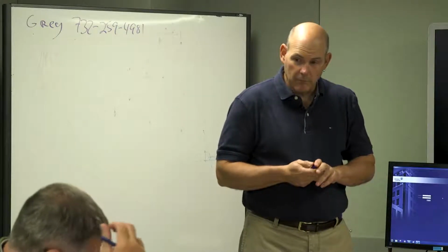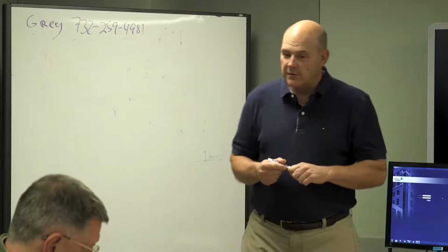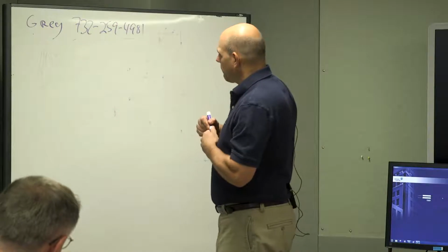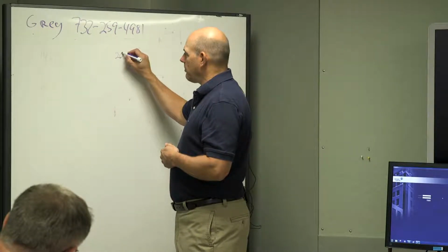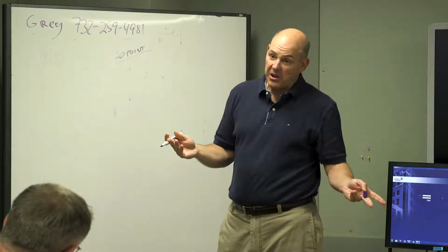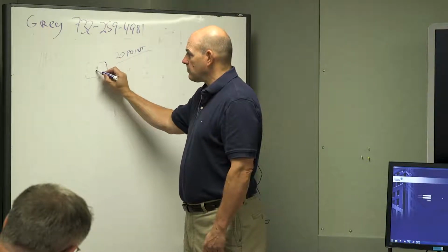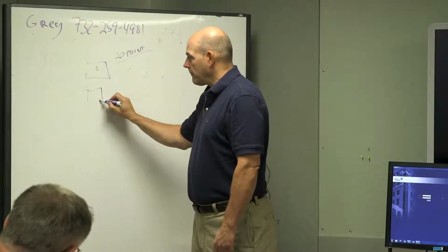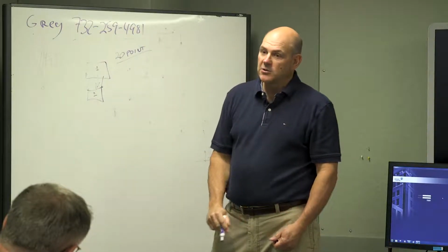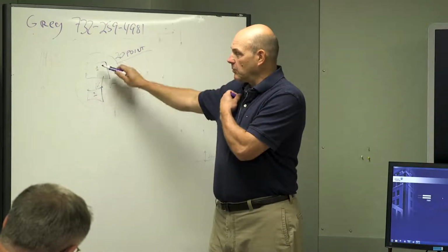For example, this is the IOM, just to make it more understandable. I'm trying to think of a good example. All right, if we have a controller that can only handle 20 points, I'm using that as a fictitious number, but we need 30. We can take this main controller here and call it address 1, and we can take an IOM, it's a baby, and call it address 2, and they will talk to one another. So we want to keep this all together because all the points here have to communicate with one another.